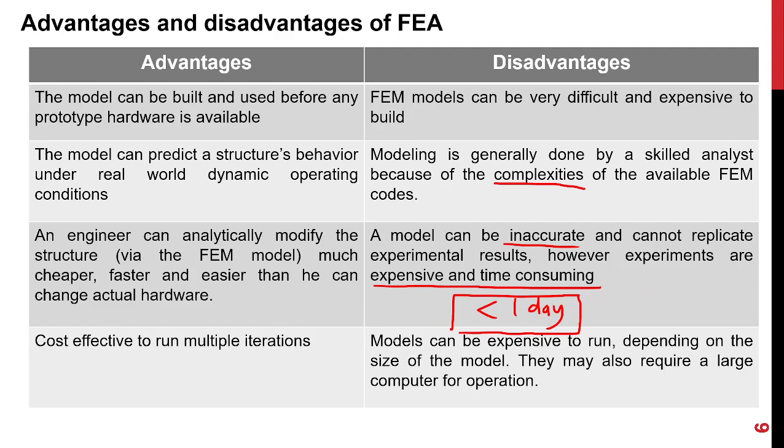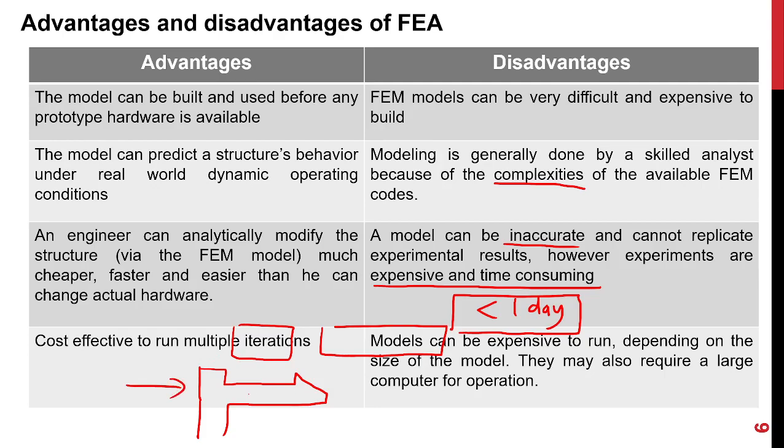But if you are designing things on the fly, you need results in less than 5 minutes. If you are designing a part, this part needs a beam like that. What is this used for? Maybe this is used for a snap fit. You want to put the part inside, so this one has to go in and this thing will flex. You want to know the cross section, what thickness is suitable. Would you take several hours or a day for something like this? No. You need maybe less than 5 minutes.